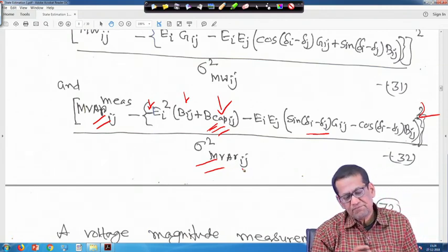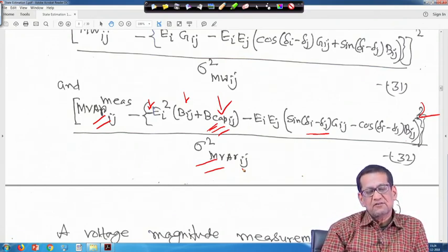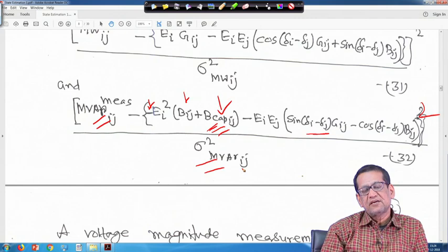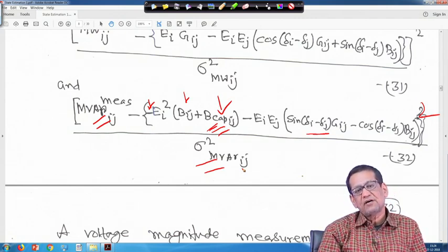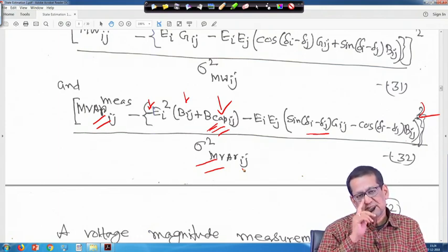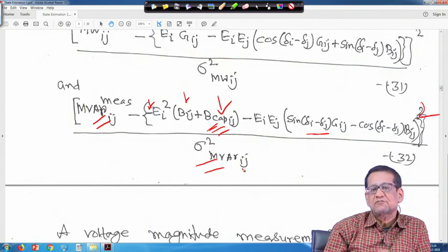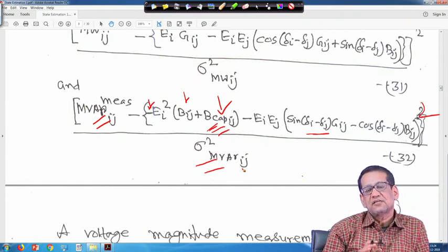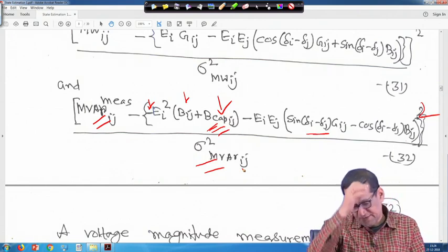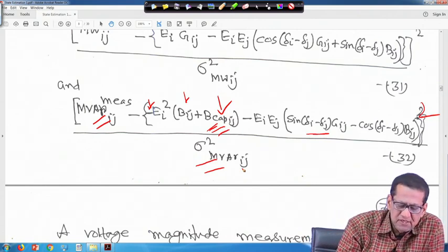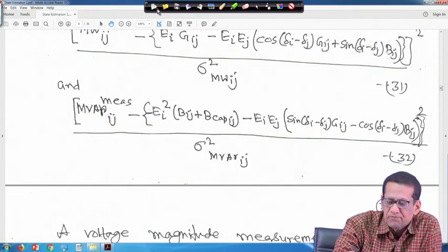In the case of real power, there is no need to consider any shunt or series capacitors or anything, right. But when you are trying to find the reactive power, when you are writing the mathematical equation, if it is a series compensated line, then you have to also consider the capacitive reactance and the susceptance, right. So this is your megavar Ij. This way you can put it in mathematical form.